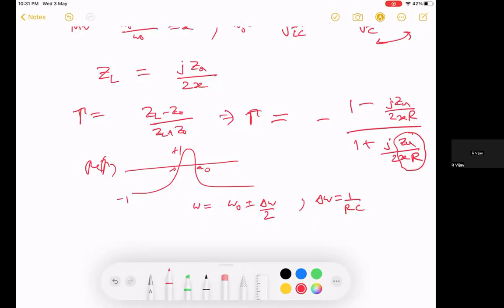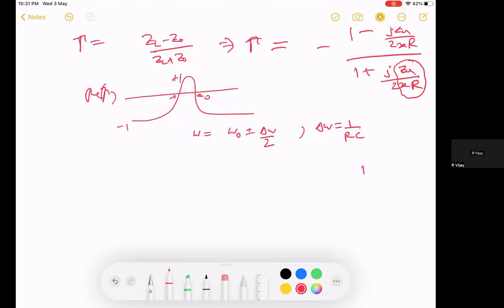It then moves on to the case where you now add another resistor here, which is called R internal, and then this is again connected to the Z0 50 ohms. So you just have to modify the expression, the ZL, by adding one more term R here, and you will see that R basically just gets clubbed into a new R prime here in parallel, and everything else remains the same for some part of the thing.